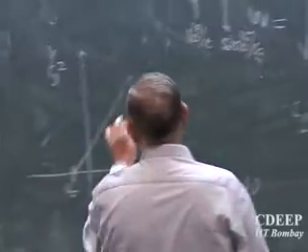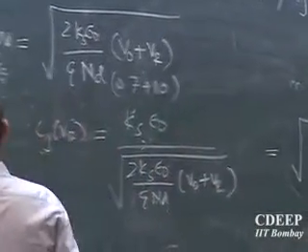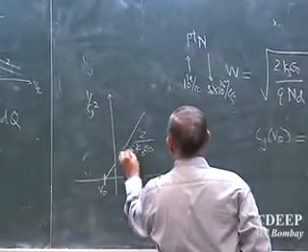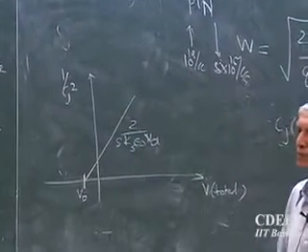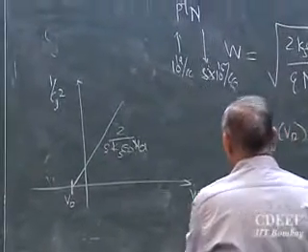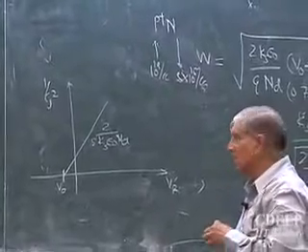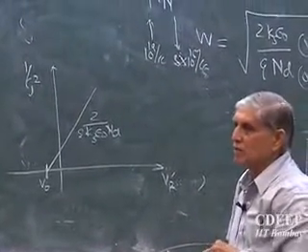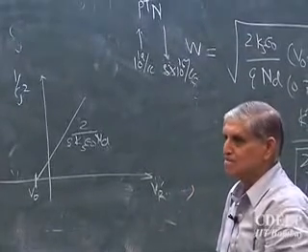What is the slope of this? 2 upon Ks epsilon naught Q ND. This is the slope of this curve. The x-axis is reverse bias, sorry, total VR. So if I monitor the slope, what do I get calculated from that?